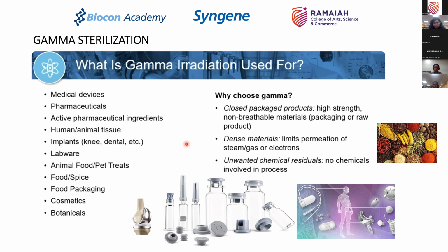In such a situation, after the product is formulated and filled into syringes, we send the entire syringe for gamma irradiation and make it compliant to the sterility assurance level required, which is 10 to the power of -6 minimum. Of course, it's with a 12D overkill approach, so 10 to the power of 12 is what is monitored. This is a very expensive product from a treatment perspective, and therefore it is very important that we have effective gamma irradiation of the product.